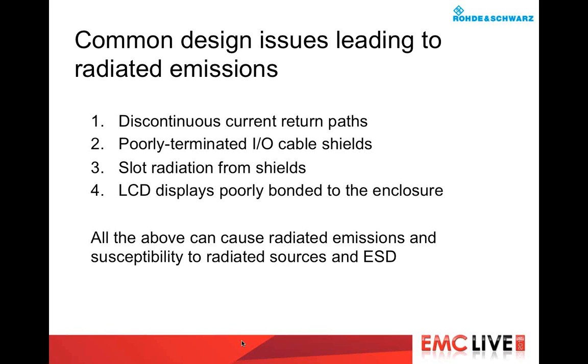Poorly terminated I/O cable shields, that happens so often. It's something that's easily solved, but I run into it all the time. Poorly designed shielded enclosures leading to slot radiation, and then LCD displays.